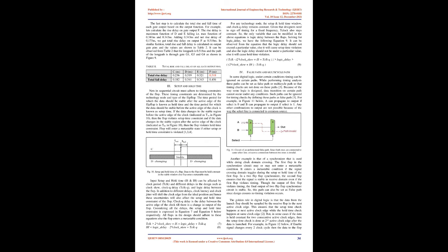For any technology node, the setup and hold time window and clock-to-Q delay remain constant. Given that designers need to sign off timing for a fixed frequency, the clock period also stays constant. So, the only variable that can be modified in the above equations is the logic delay between the flops. Solving for logic_delay, we have the following equation 9.